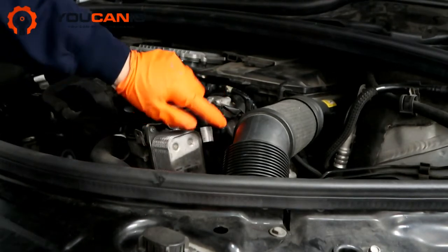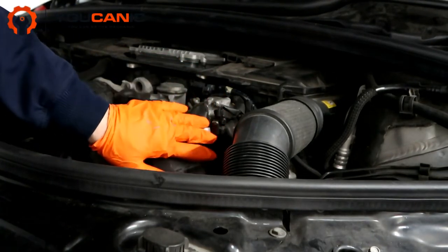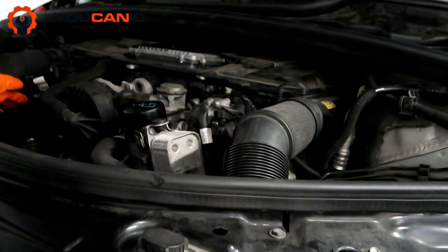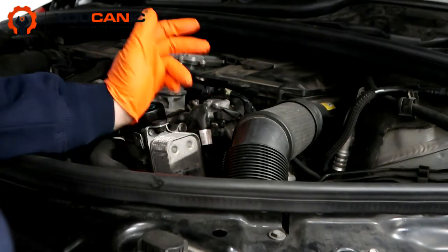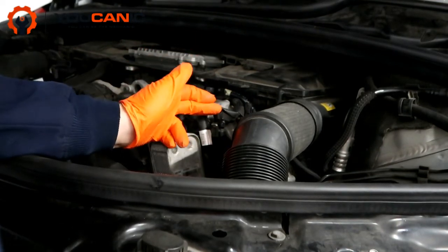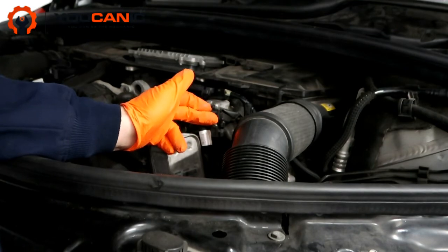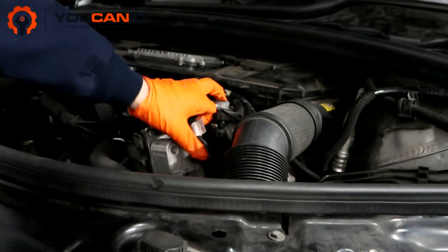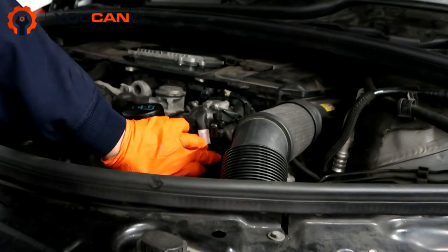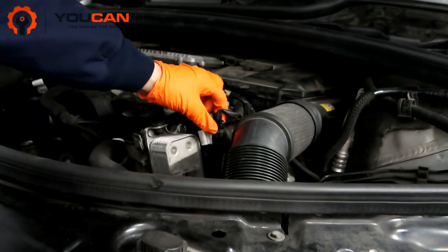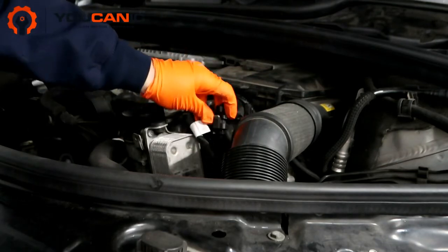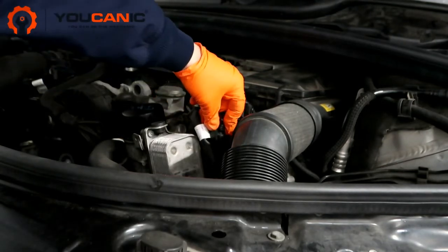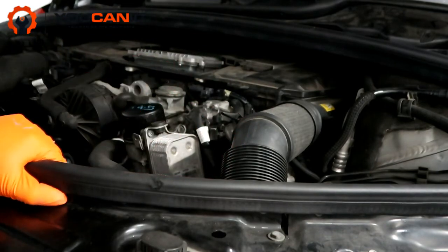Then here we have the camshaft position sensor. Now this vehicle has 4, 1, 2 on this side, 2 on this side. V6 engine. But with that code, if you research that further, you will be able to find that it's this sensor right here. And honestly, to replace this one, all you have is a Torx bolt right here. You take that off, you disconnect this connector, and then you simply pull this out and replace it. It takes 15 minutes at the most. So something like that will be really easy. Of course, if it's your gas cap, it will be really easy as well.